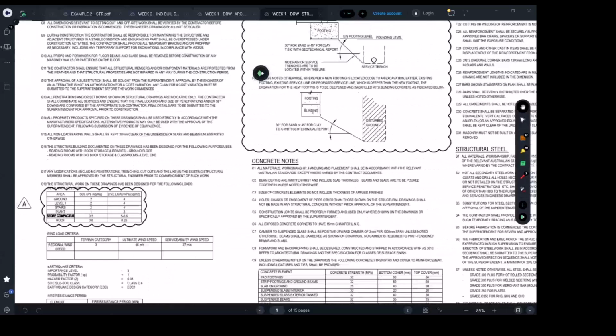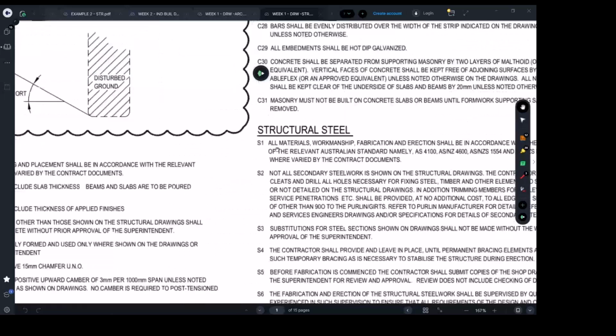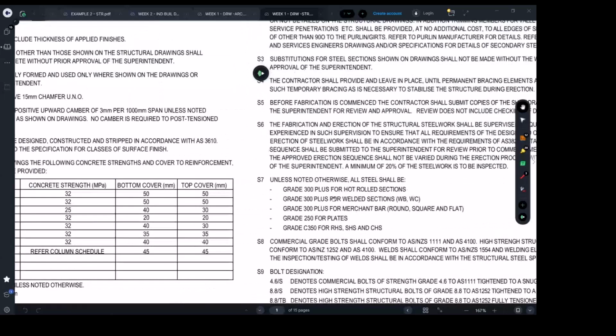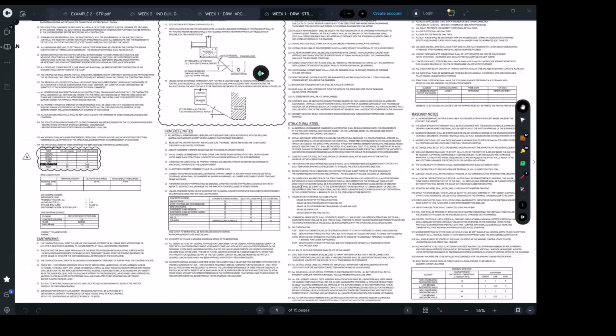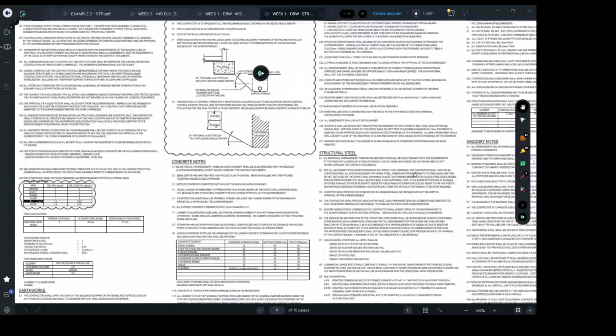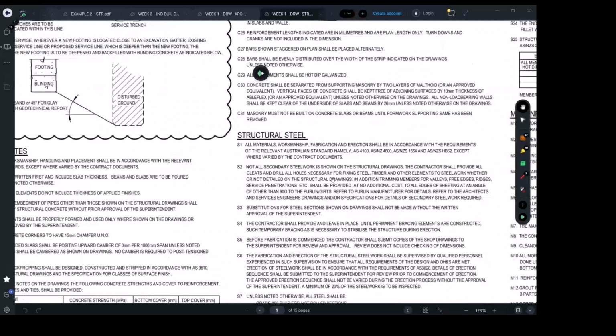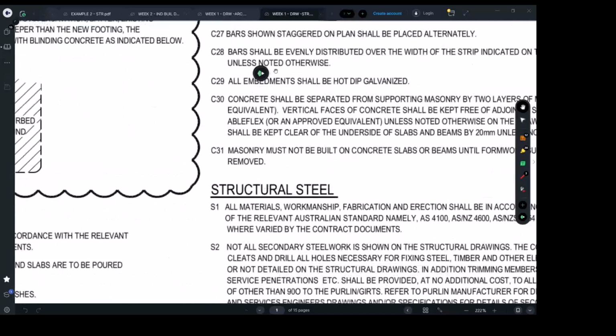to understand what the limitations are. For example, under the steel structure sections, the engineer somewhere here will tell you that any steel column you're going to place outside in the environment, you have to galvanize it. You have to protect it from corrosion, right? This is now the construction engineer's liability, because they have been given this instruction. The engineer won't be saying this inside the tables where they specify the steel beam, and there are many other things.